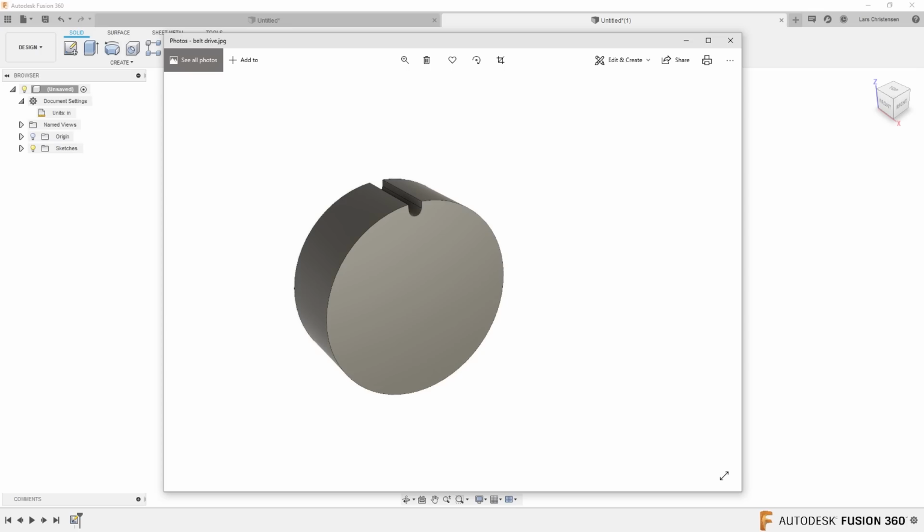So this groove here is for a tooth, for a belt, and the sides inside the tooth are a little angled. So using a 2D contour, I can't get that geometry. Using trace will keep the wall straight. Philip has a VF2 mill and a lathe. How would I machine this?